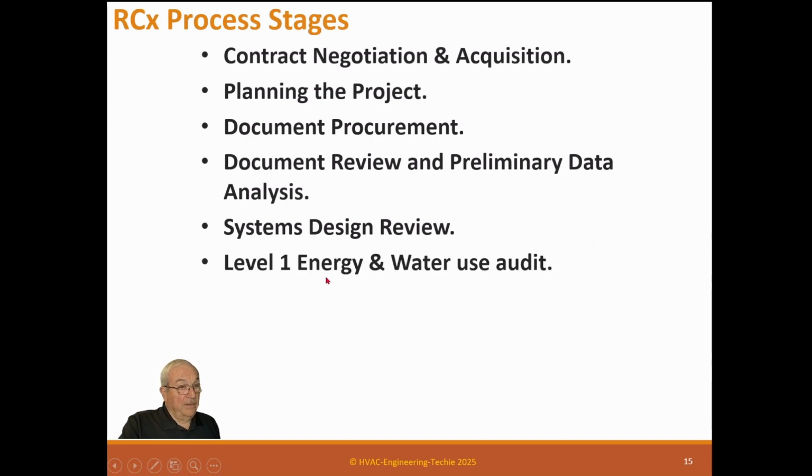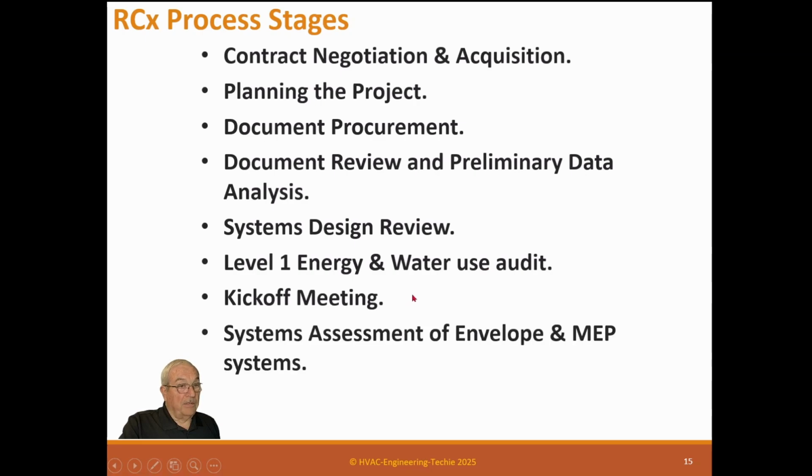You're going to do a level 1 energy and water audit, and for that you need the power bills and the water bills. You're going to have a kickoff meeting, which is really important, and we'll talk about that because that lets everybody know what you're doing. System assessment of envelope and MEP systems. So you're going to go through and assess the systems. You're going to do occupant and operator interviews. You're going to talk to people.